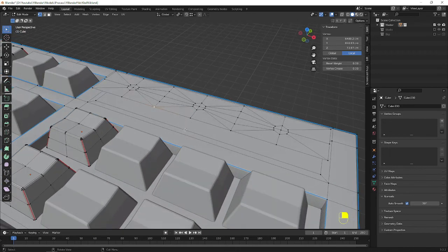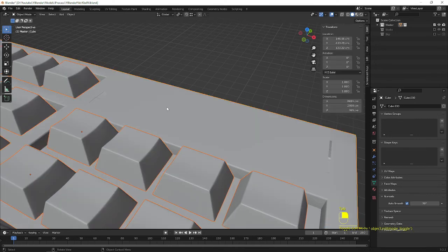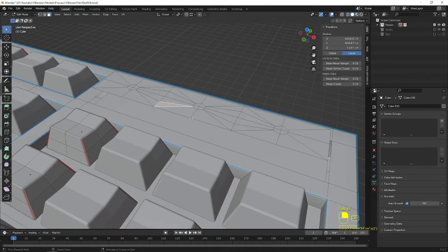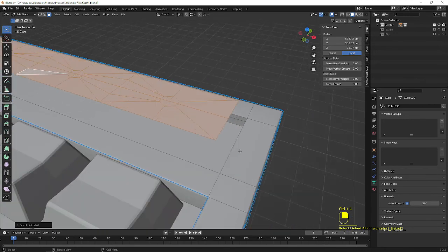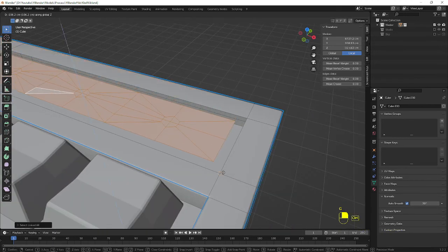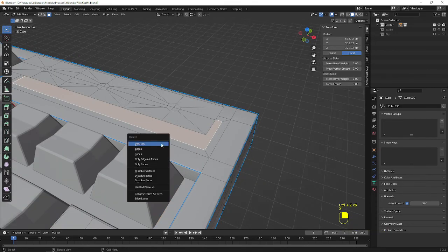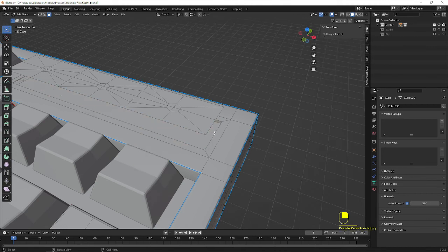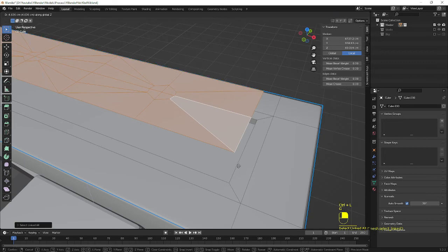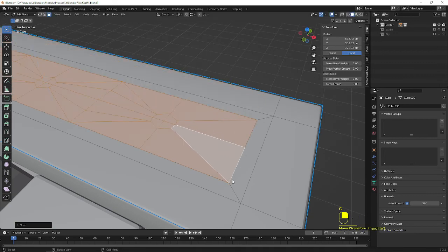Okay, now go to the face selection, select the face X to delete the vertices, and select this one, press Ctrl L and GZ to move till here. Okay, actually I missed out something here, I just undo it. X, delete only the faces. Now select this, press Ctrl L and GZ to move up to here.